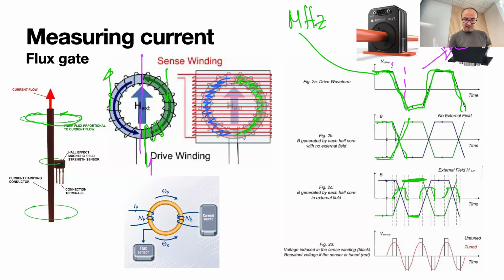And this will cause imbalance in the toroidal core anyway, and this will, in essence, induce some minute current on the wire itself. So the wire itself will conduct some DC value, and these small coils will induce on top of it some form of excitation signal. And then we can measure the voltage, and then we can do the impedance measurement.